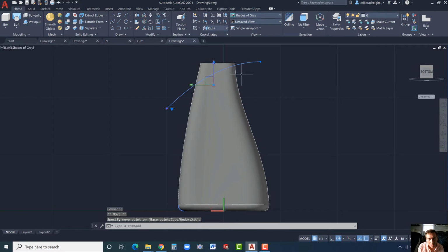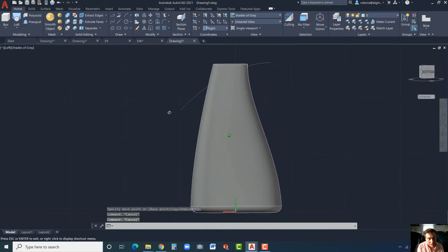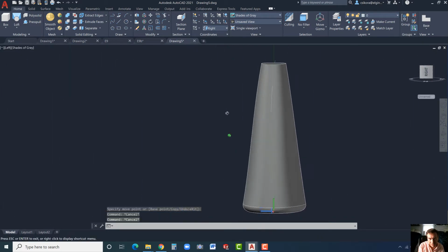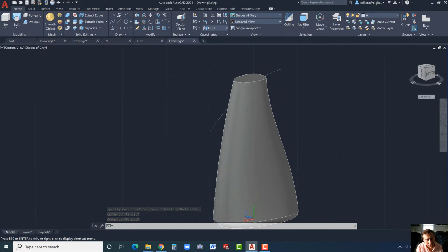Click, because we're going to use that to shave this. All right, hit escape, rotate it, and make sure it's not 3D. It should just be a 2D curve. If you do have difficulty where it's actually starting to curve like that, you won't be able to extrude it. So I would recommend going back to the snap-on mode to smooth it out. Just delete it, draw a new one.